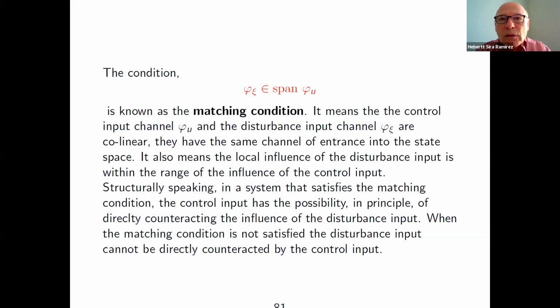Also in passivity-based control, you further increase the dissipation of your system in order to attenuate the effect of the unmatched disturbance reflected to your control input span, which, in the case of passive systems, is also a relative degree 1 type of condition. And it is true.